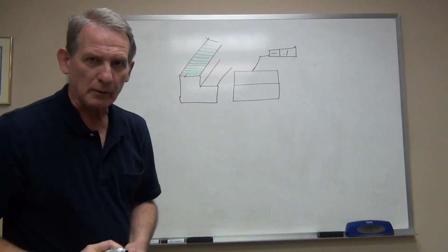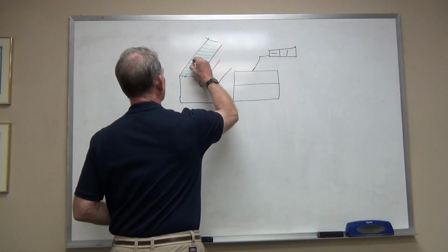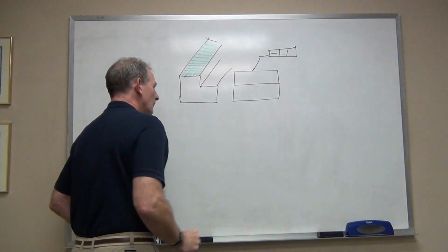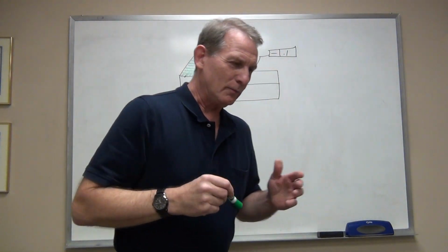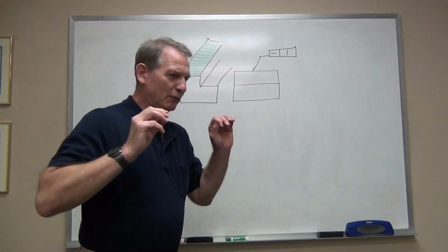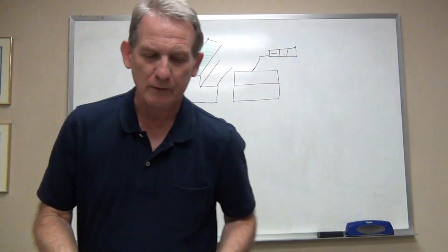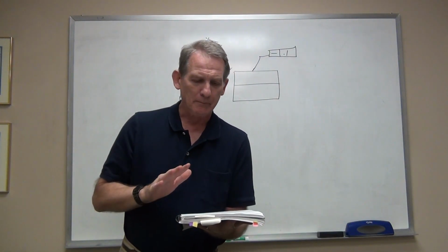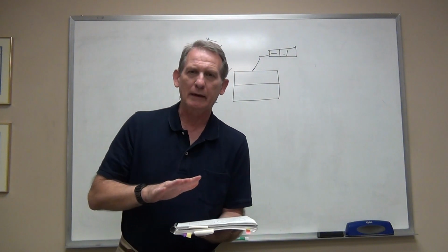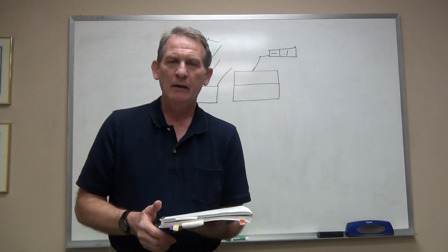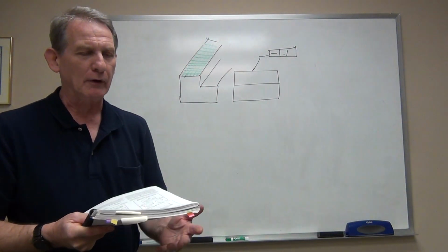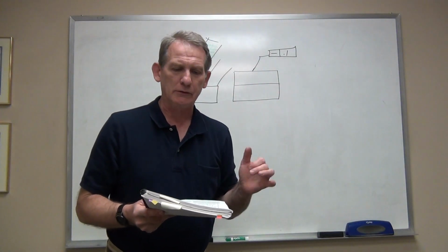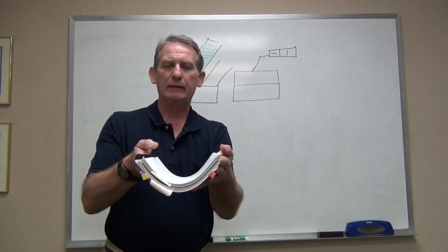The 100 thousandths requirement applies to lines that are running in this direction. So if you picture that geometrically, you can sort of think of it as this book, and this page being a plane, a geometric plane. And what would happen if I had two different linear straightnesses on this part? Well, it would look something like this.